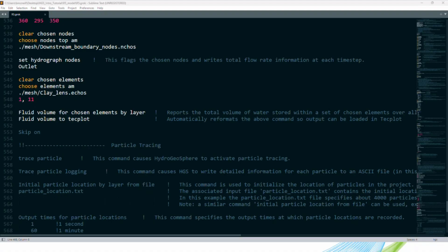So the reactive transport capabilities are pretty run-of-the-mill, first and zeroth order with potentially multiple solutes tracked in parallel, but relatively simple, no complex reaction kinetics with multiple different solutes. We do support also density-dependent flow, which can be a product of saltwater intrusion or seawater simulations, which is one of the main use cases there, but it also can potentially be due to just really, really high concentrations of really any solute.